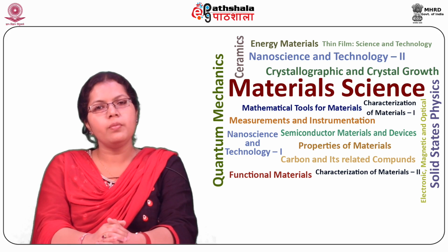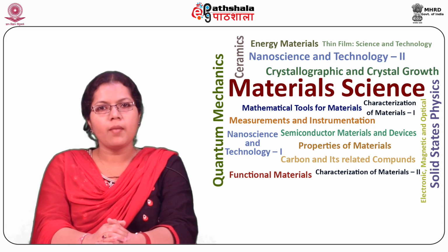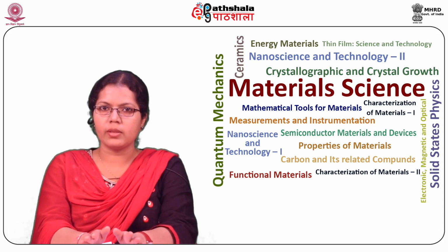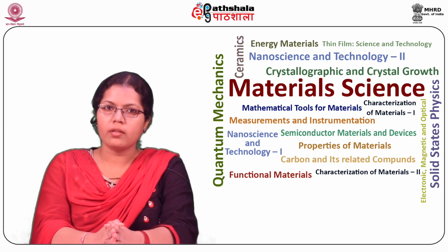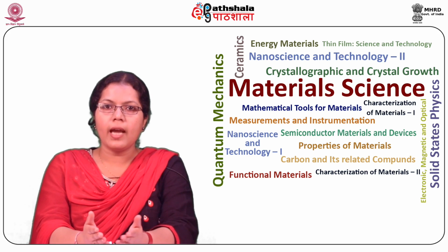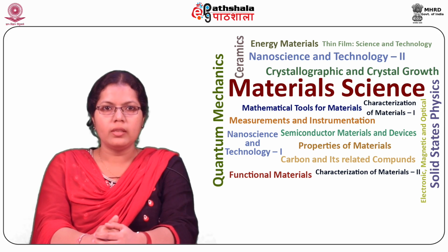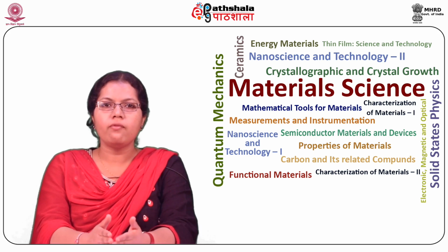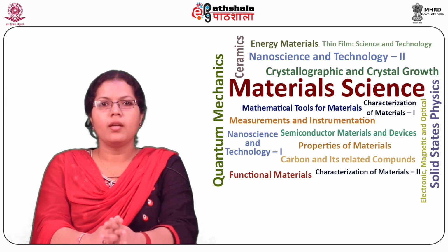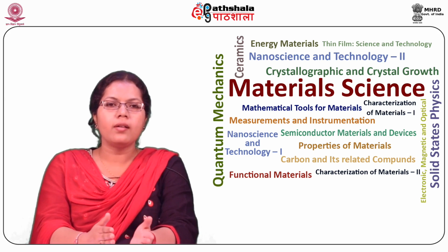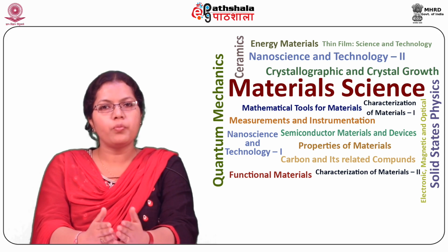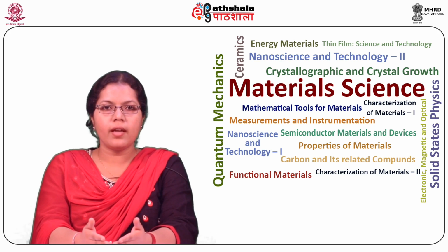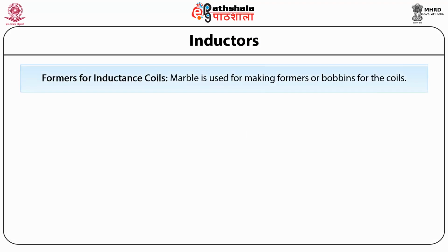The inductor should be so designed that capacitive effects are negligible. This is particularly important for inductors working at higher frequencies, where the inter-turn capacitance may drastically change the effective value of inductance. The inductor should desirably be unaffected by external magnetic fields and should produce a minimum interfering field of its own. Formers of inductance coils.